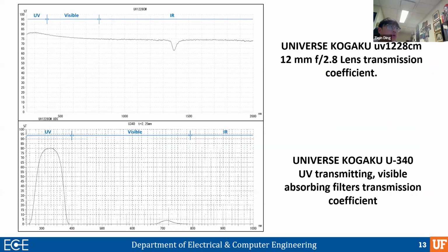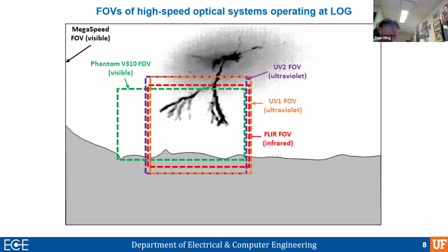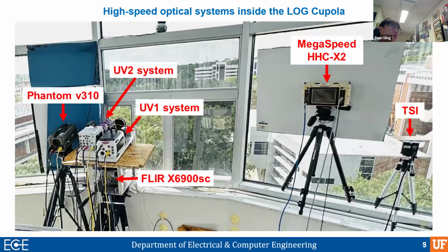let me show you. So we use an image intensifier that is coupled to the Phantom camera behind it. The intensifier is capable of doing high speed gating, and we use the Phantom camera to image the output of that intensifier. There will be a phosphor at the output end of the intensifier, and then you don't require an optical lens to image that.